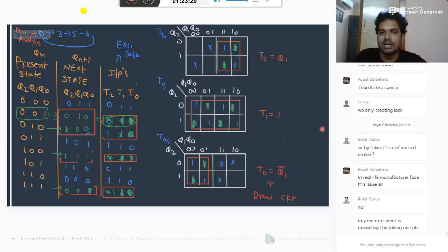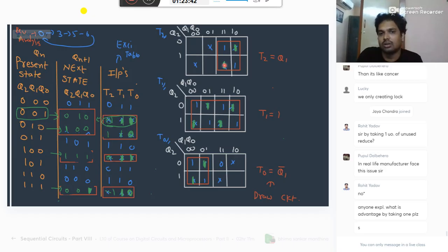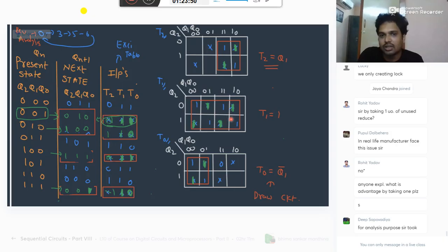What is your doubt, Rohit? Ask me clearly. Why I have taken here one is your doubt because you have considered in the K-map. In the K-map, in the quad you bubbled it. Bubbled it means you are considering it as one. Why you have taken this as one? Because of minimization of your equation. If you don't take this whole octet, then you get an XOR gate. Because of this octet, you are getting one. So in the SOP expression, if you consider in the quad, it is 1. If you neglect in the quad or pair, then it is 0. This is the K-map basic.